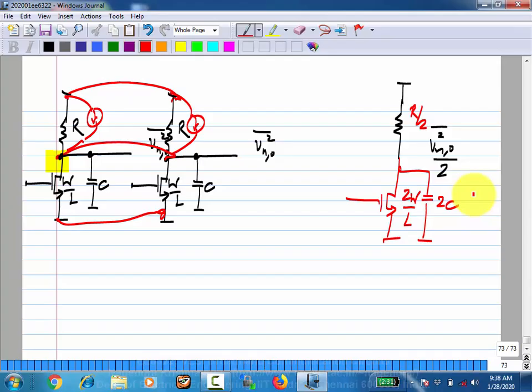I mean, if you are able to invent a new circuit, that's fine, but here I am talking about when you have many parts of a circuit. Let's say this part is contributing too much noise and some other part is contributing a very negligible fraction of the noise. What you may be able to do is scale up this part of the circuit so that it contributes less.